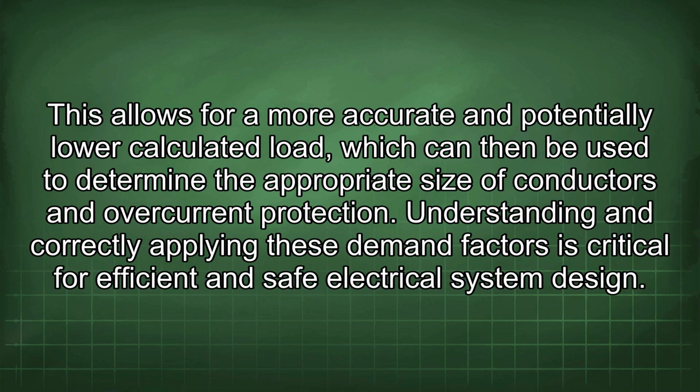This allows for a more accurate and potentially lower calculated load, which can then be used to determine the appropriate size of conductors and overcurrent protection. Understanding and correctly applying these demand factors is critical for efficient and safe electrical system design.